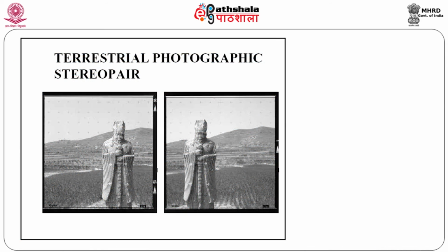And as I told you last time itself, in the previous slide I showed you long back, here is how this is taken, and all these things are done using your cameras, which may be either terrestrial in nature or aerial in nature. But the bottom line is that we require two sets of photographs to have a stereo pair, to have a depth perception, to understand the depth, otherwise it is not possible.